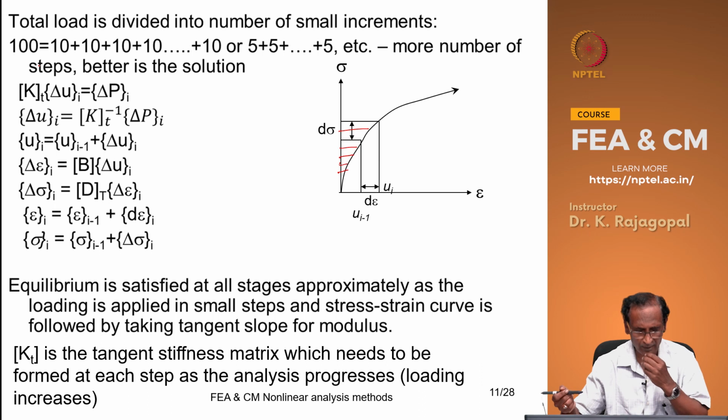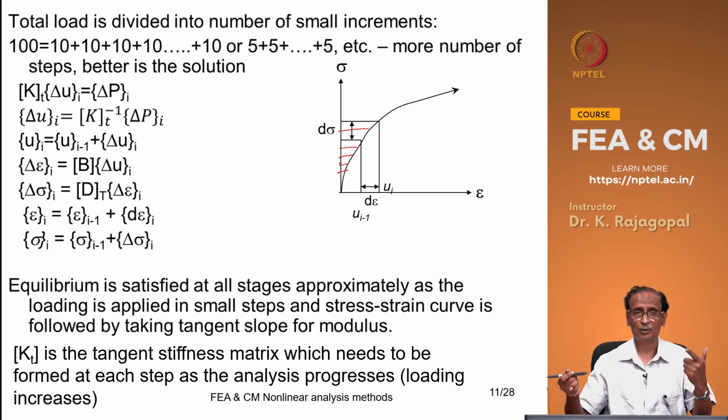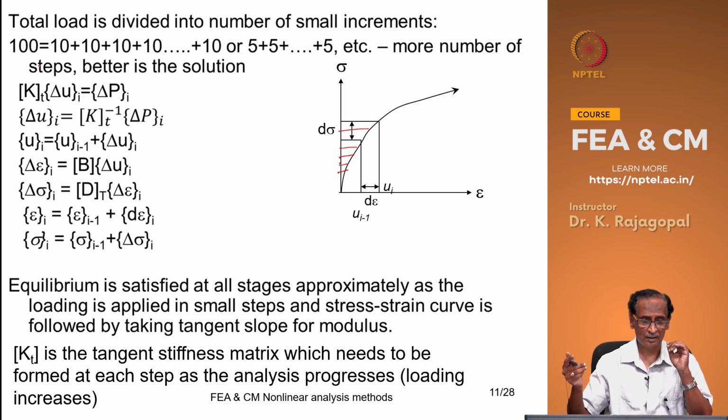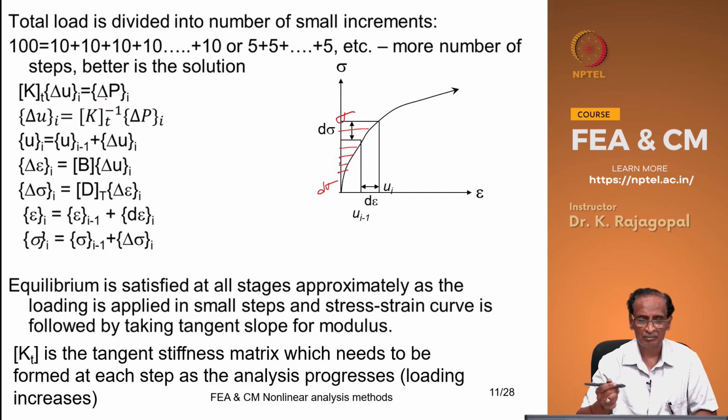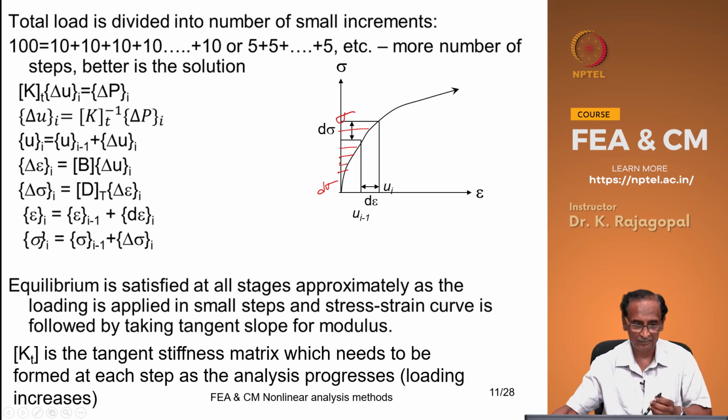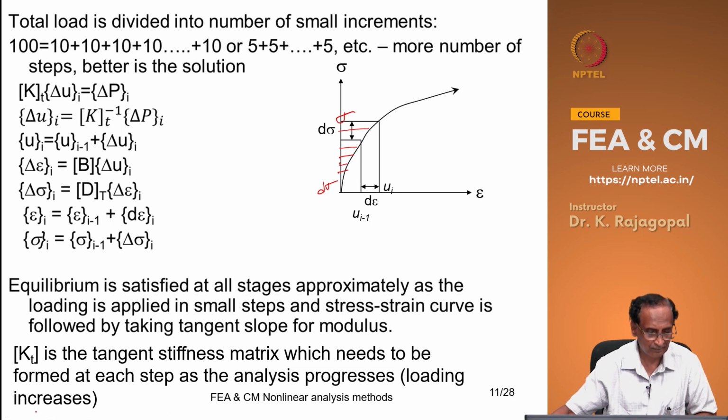So, instead of doing the analysis one time, we are going to repeat it several times. So, that is the main difference between our linear elastic and this non-linear elastic or the inelastic systems. And now we are not going to apply the total stress in one go. We are going to apply this in small steps d sigma, or corresponding to that your incremental load of delta p.